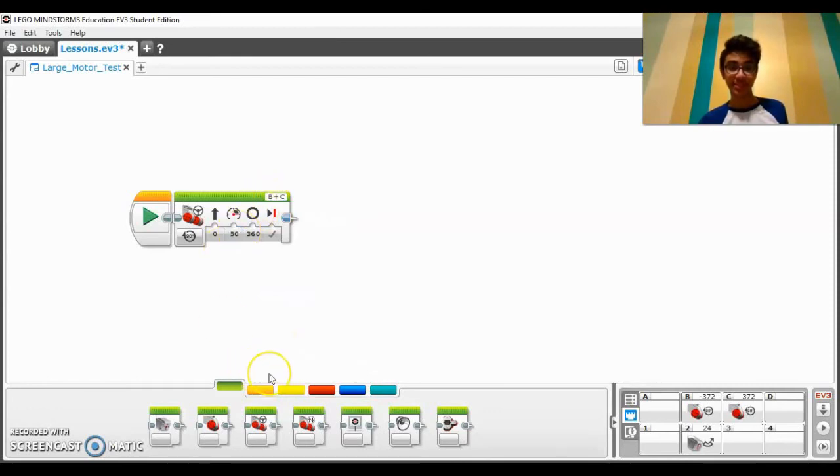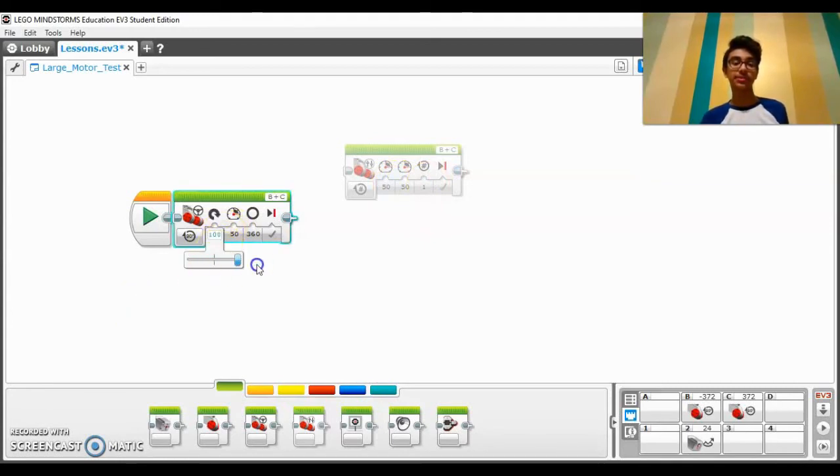And the reason I say this is if I, for example, have the two commands side by side, a tank command allows you to vary the speeds exactly how much you need, whereas a steering command tells you how much to add or subtract from each motor. And you can see that cool symbol spinning around as I vary that number. This just tells your robot how much of a curve to apply to your wheels.